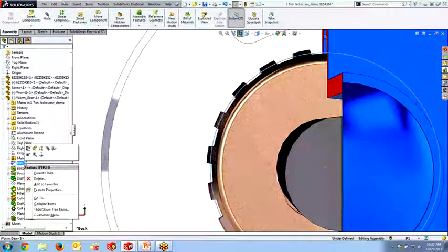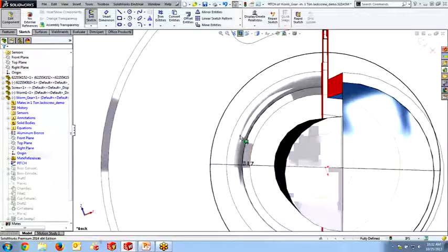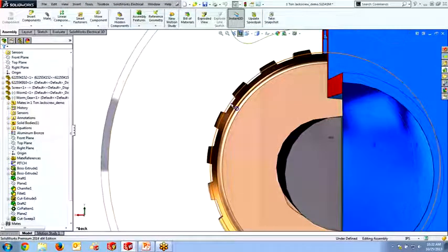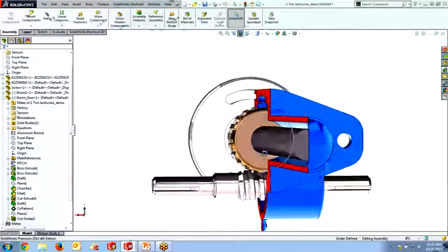It's a very, very simple sketch. All it is is a circular sketch entity based around the center line of that gear with the pitch diameter in place. And the reason I'm going to model this is because when I mate to a gear inside of SolidWorks, I want to be mating to the pitch diameter and not necessarily to the teeth or any other geometry on that gear.